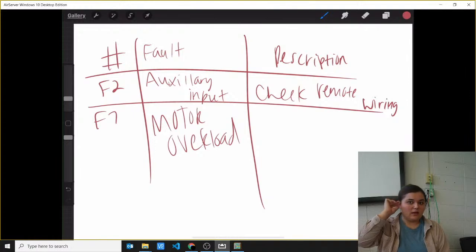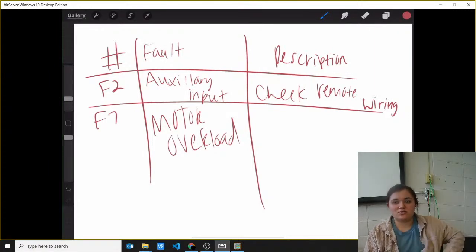That's why those things are so important, because back in the day, they only had basic stuff. They had to go out there and troubleshoot and see, well, did somebody wire this up wrong? But now you've got a VFD or a logic controller or whatever telling you exactly what's the matter. So it makes troubleshooting a lot easier. So it makes your job literally easier. And once you get to see it work in person, you'll be like, oh, this is way better than wiring up that push button.